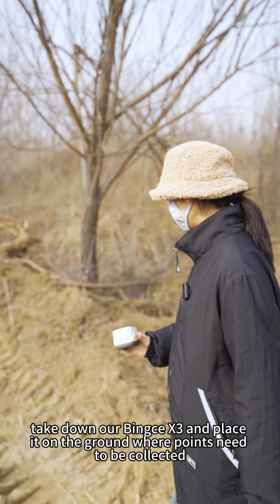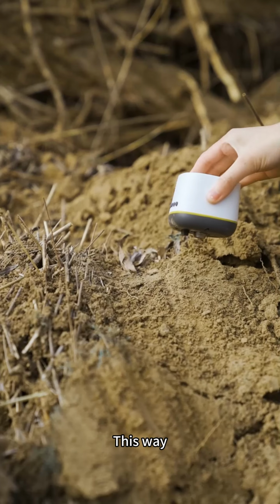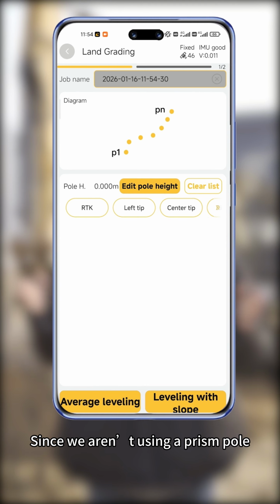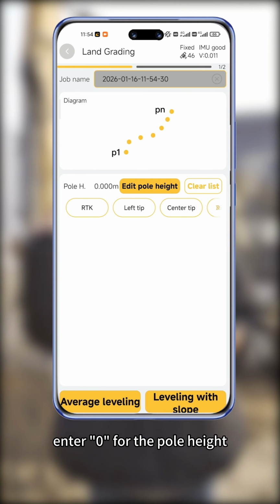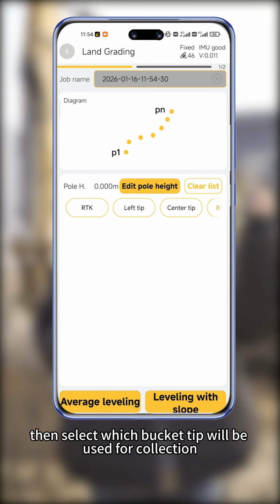Take down our Terrain Pilot X3 and place it on the ground where points need to be collected. This way, you don't have to drive the excavator around to every spot. Since we aren't using a prism pole, enter 0 for the pole height. If you're collecting point data while operating the excavator, then select which bucket tip will be used for collection.